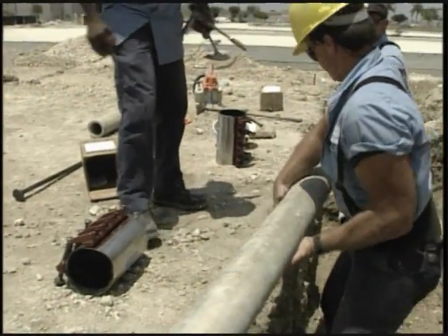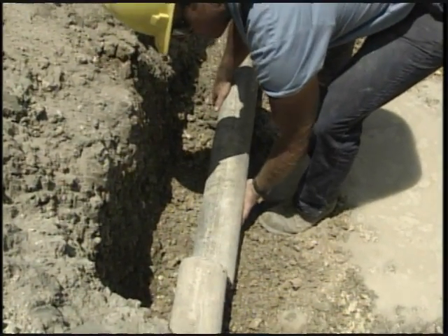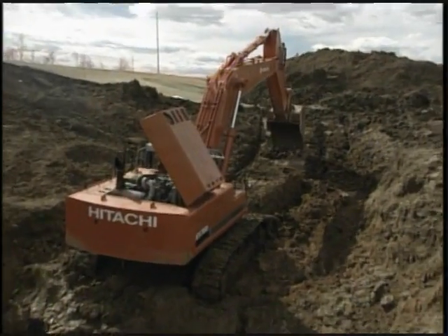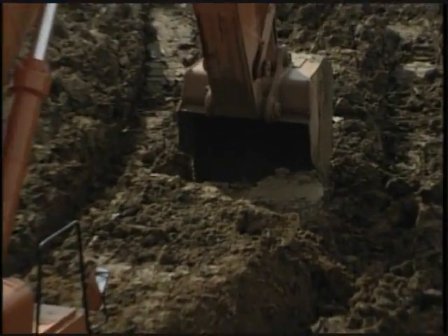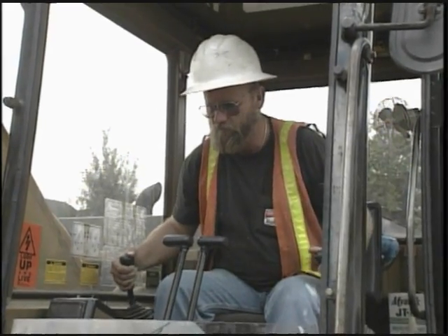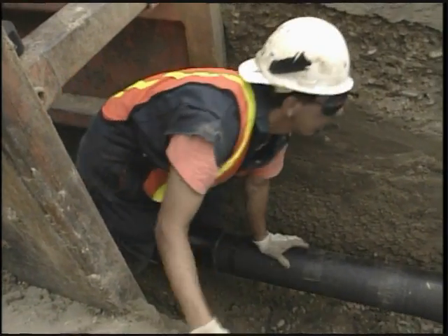If soil is granular, it probably contains a lot of sand and is unstable and likely to shift and move easily. If it's cohesive, it probably contains a lot of clay and the walls of an excavation will be more stable. Since pipeline maintenance work involves previously disturbed soil, it's usually type B soil.